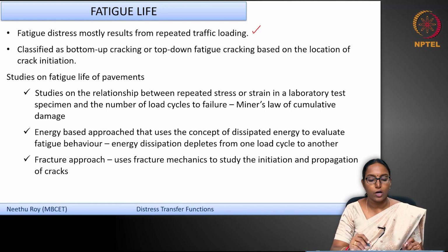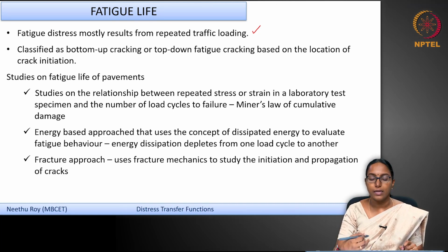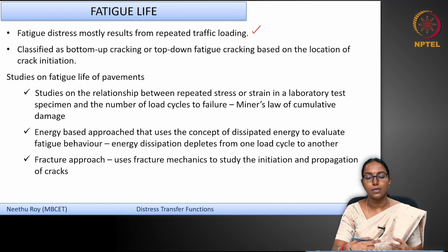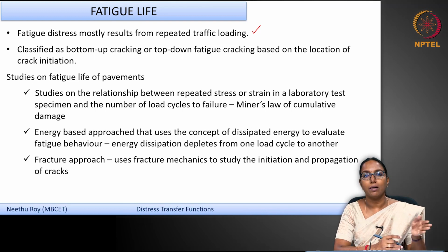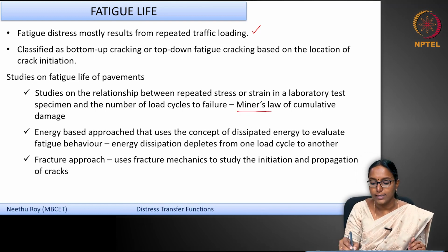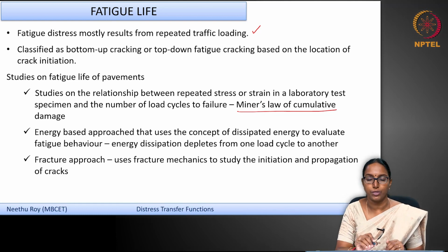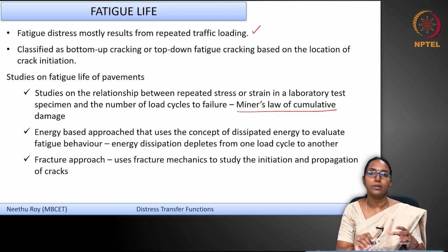Okay. So, in order to study this fatigue behavior or the fatigue life of a bituminous pavement, essentially you can have three approaches. The first one is that you see what the relationship is between the repeated stresses and strains in a laboratory test on a bituminous material and the number of repetitions or load cycles to failure. Okay. So, you call it Miner's law of cumulative damage approach. You see how each load application damages this material, and this can be accumulated to find out how this will perform in the field. Okay.